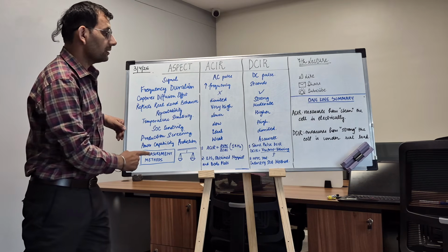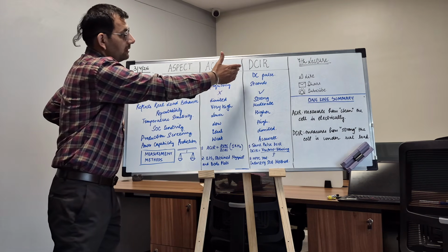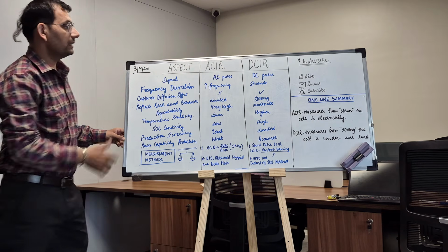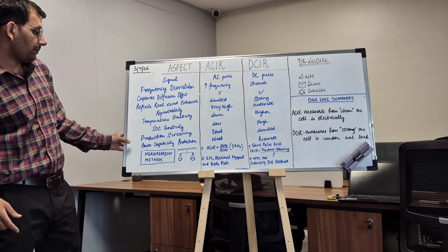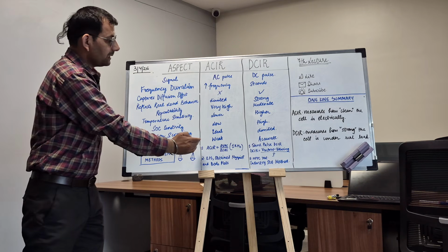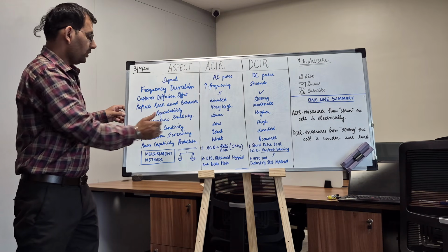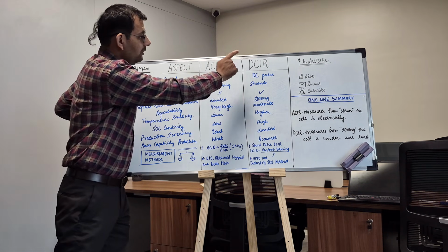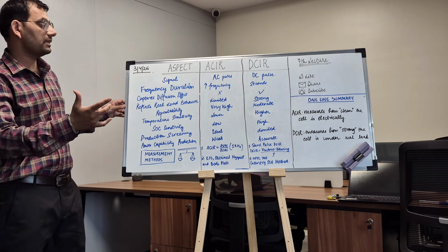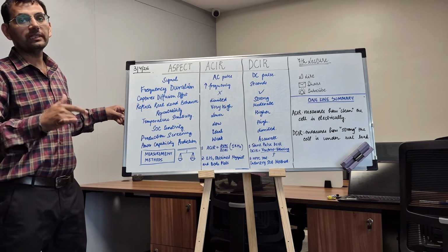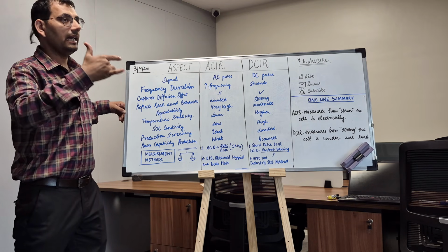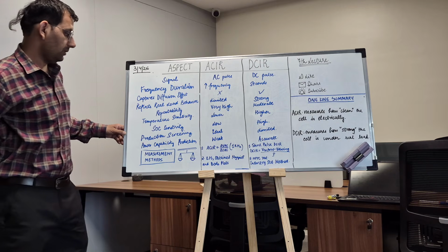So limited, there is a DCIR that I am going to use, that will be limited. I will sort the cells on the basis of ACIR. That will be the ideal value. For power capacity prediction, if I am considering ACIR, it is weak. But for accuracy, DCIR will accurately define how much power capacity is inside with respect to SOC and SOH of a cell, and how much power it can deliver, is capable of. I will get an accurate value by using a DCIR calculation.